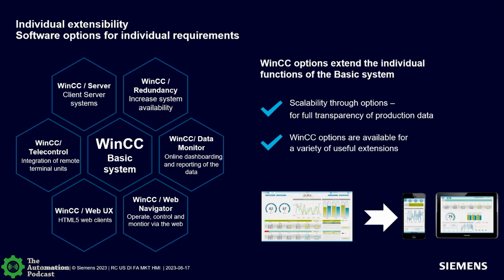It allows the WinCC station to become a server in its own right. So if you're working with a desktop operating system like Windows 11, it'll allow you to connect 3 additional clients to that server and start pulling information. If you need more than 3, then Microsoft requires a Windows server operating system.